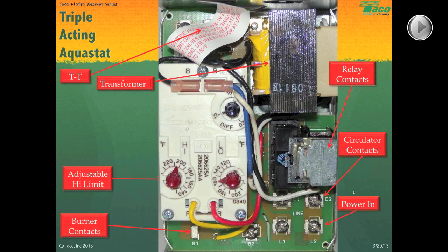You have three dials. First, you have your adjustable high limit. It's a little more formal. It's a little red dial, and you can actually read the numbers there, ranging from 140 to 220. You also have your adjustable low limit. What minimum temperature do you wish to maintain in that boiler? Let's say you want to bop between 200 degrees on the high limit and 140 degrees on the low limit. Okay, that's your high limit, low limit. Again, whatever it needs to be is whatever it needs to be.